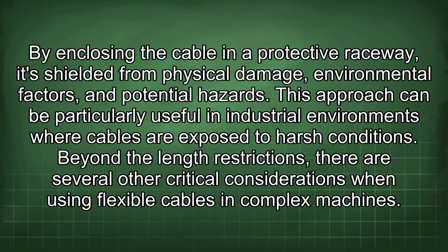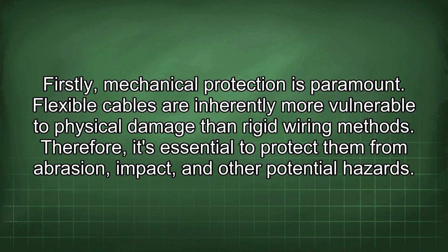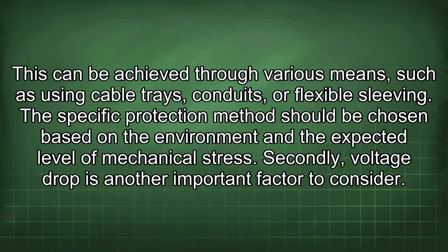Beyond the length restrictions, there are several other critical considerations when using flexible cables in complex machines. Firstly, mechanical protection is paramount. Flexible cables are inherently more vulnerable to physical damage than rigid wiring methods. Therefore, it's essential to protect them from abrasion, impact, and other potential hazards. This can be achieved through various means, such as using cable trays, conduits, or flexible sleeving. The specific protection method should be chosen based on the environment and the expected level of mechanical stress.